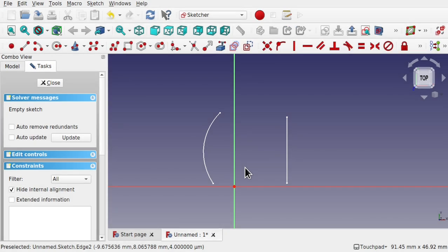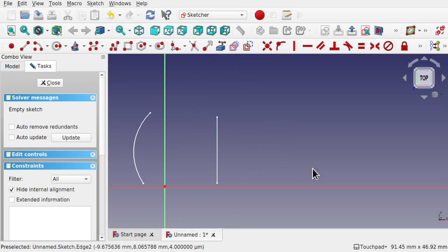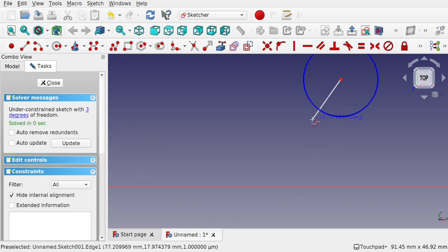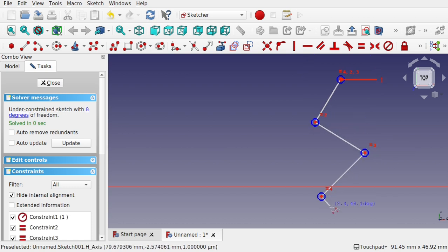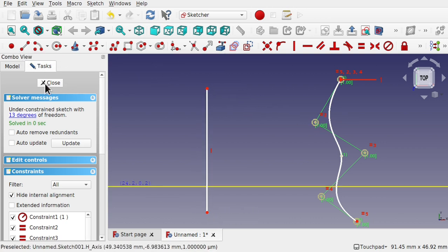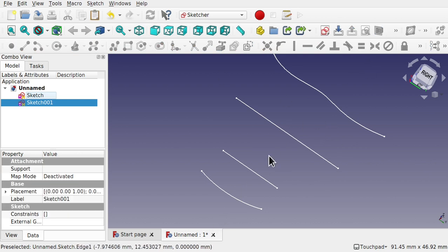And XY plane that can be in different planes if you so desire. And we've got that one as a guide. So let's create something a bit different. So let's go for a B-spline again. And this time something a bit curvy. And we'll need to go for a line here as well. So we've got these two sketches. We need to create a ruled surface.